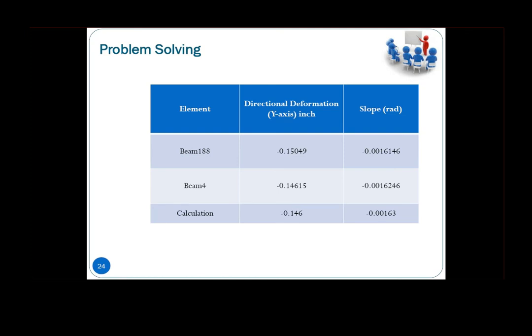So what we did, as I mentioned to you, is Euler-Bernoulli. Okay, so ANSYS now is already using Timoshenko beam models to solve it. Of course, you can still use Euler-Bernoulli, where we call this beam 4. Beam 4 under ANSYS is under Euler-Bernoulli beam models. If I call this out, then probably I have very close results to my manual calculations. Our model is Euler-Bernoulli beam models.